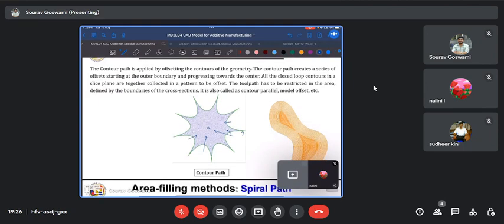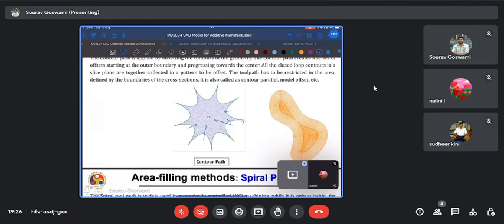While this gives very good density and very good printed characteristics, one common defect which can be easily guessed is that for certain complex shapes, it might leave voids, such as can be seen in the example to the right. So in all of these regions, we have these voids.